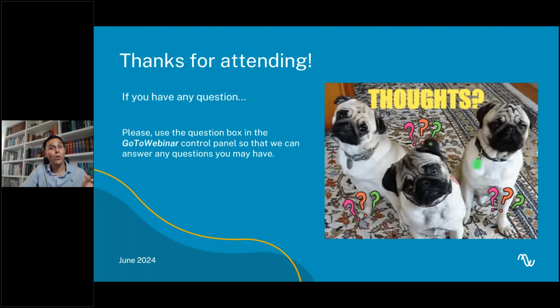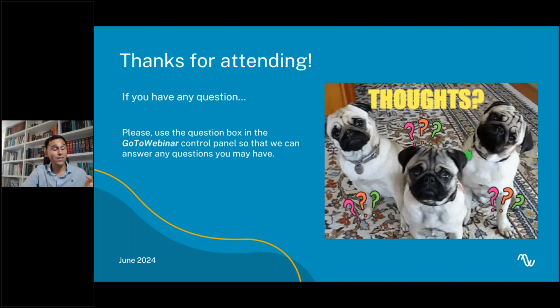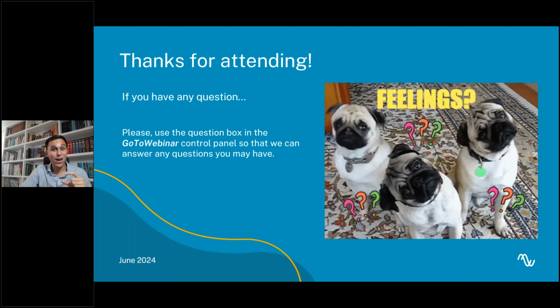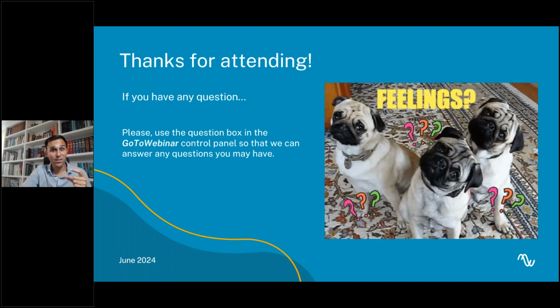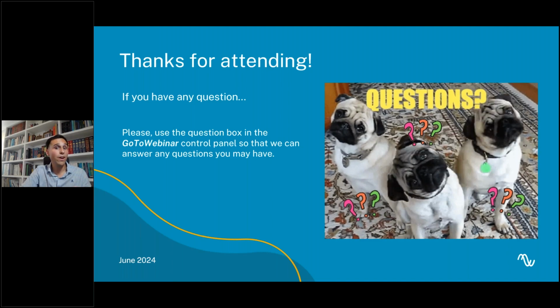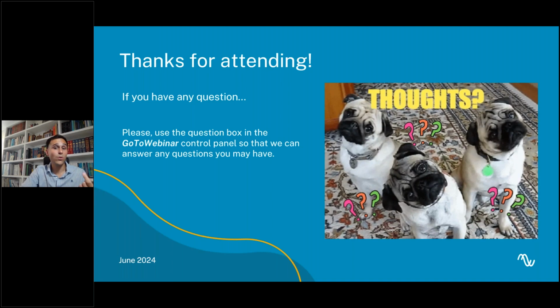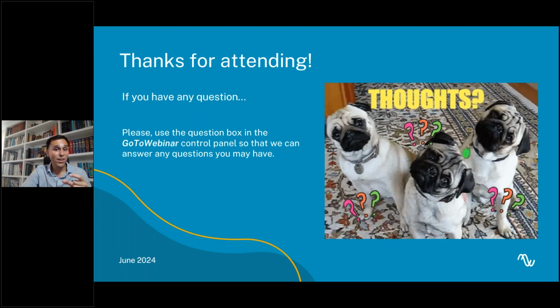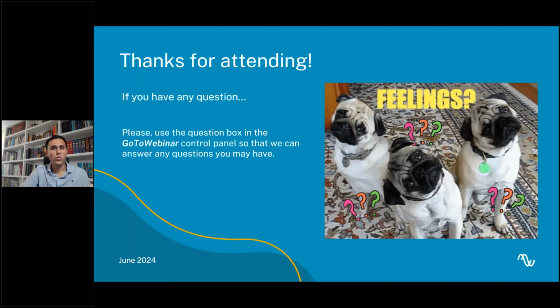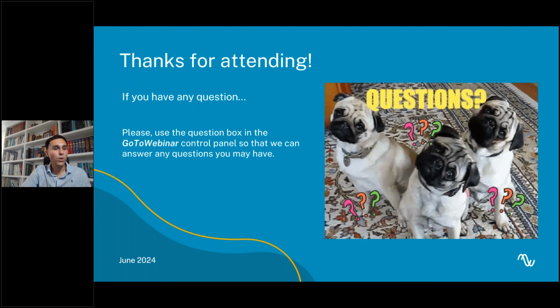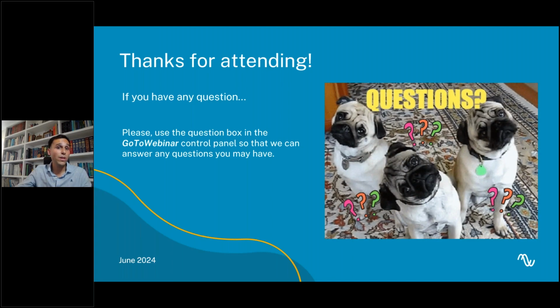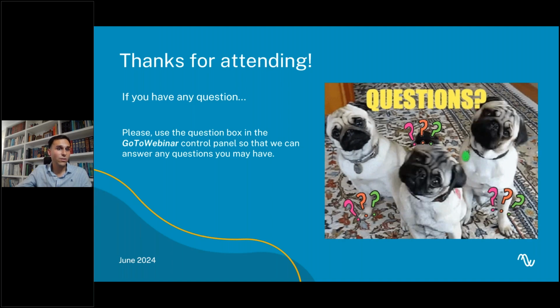If you upload a grid, a digital elevation model, with a higher resolution than 1 meter, for example 0.5 meters, the software won't use this information. So the minimum distance will be 1 meter, and you won't add more precision to the calculation. So you have to be aware also of the minimum distance between piles.